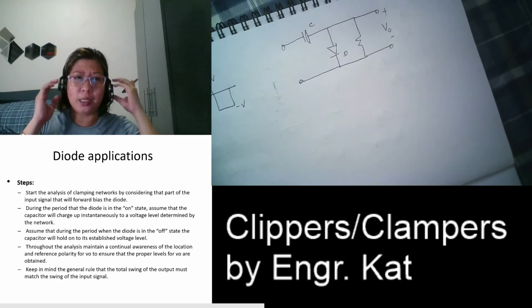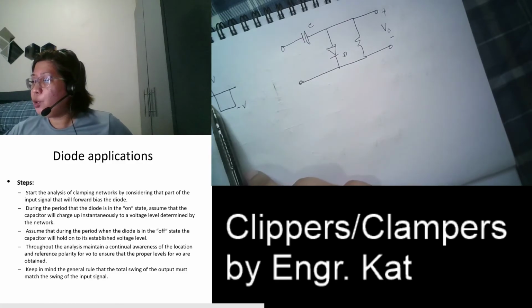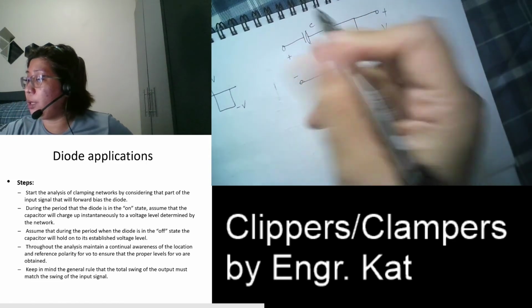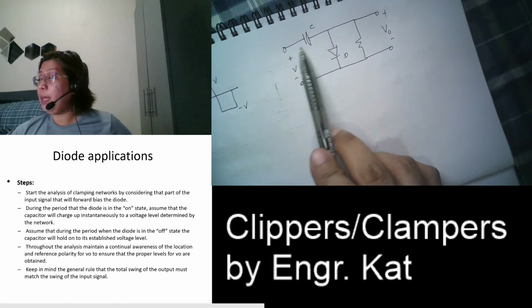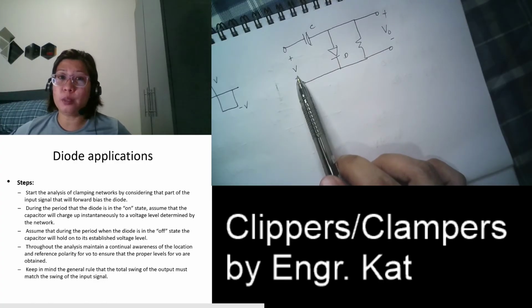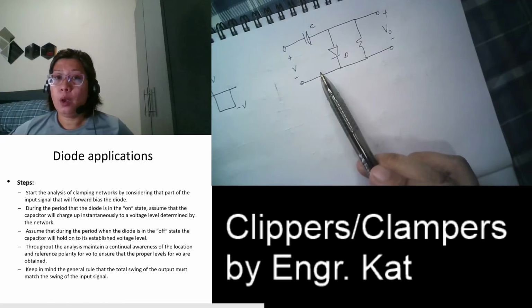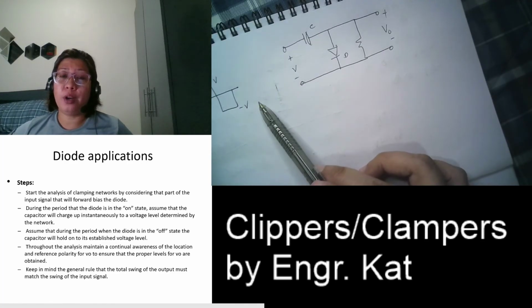Okay, in the analysis, here, we really have to start. For example, during the positive half, we have here plus and minus. This is V. So will this make your diode forward bias? If yes, we can start right away. But if this makes your diode reverse bias, we have to remove it and go to the other half cycle.